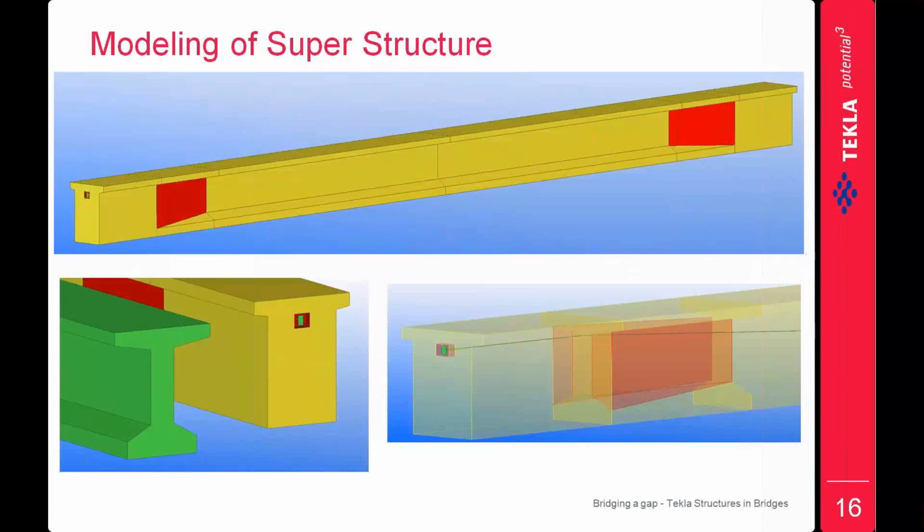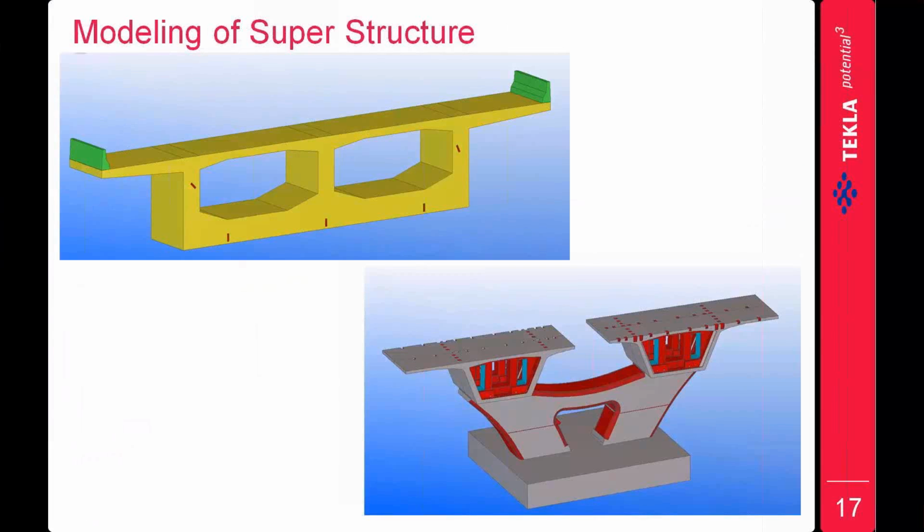And even with the I sections, you can see over here one complete I section, and then one of the tendons modeled over here with the end blocks. I just modeled only one single tendon here, so that we can see clearly the details in the model. And then the segment side. We can model the segments if it is a straight stretch or even in the curved portion, and we can model very quickly the user-defined shape of the segments, and even we can repeat the same.